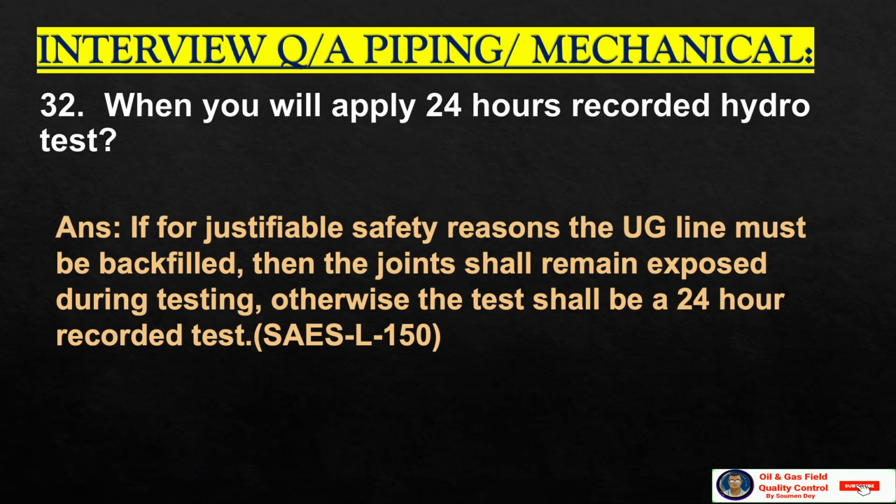When will you apply a 24 hours recorded hydro test? If, for safety reasons, the underground line must be backfilled, then the joints shall remain exposed during testing. Otherwise, if we need to backfill the joints also, the test shall be a 24 hours recorded test as per SAES-L-150.